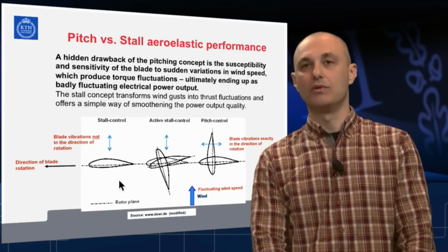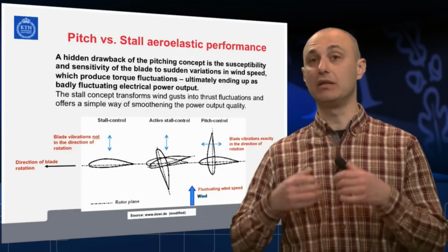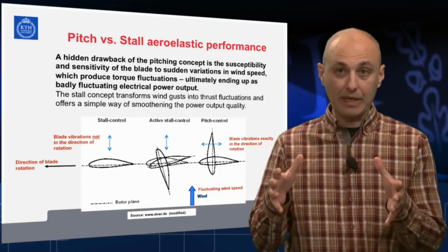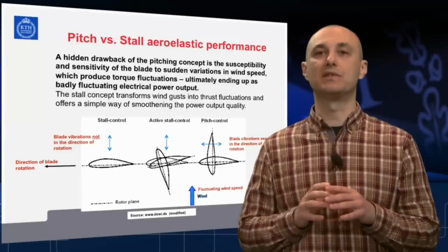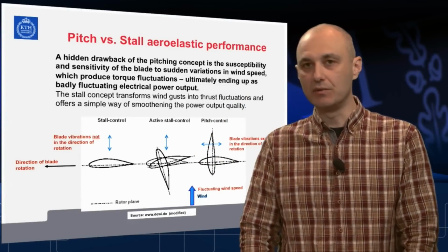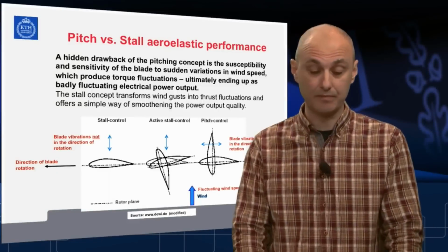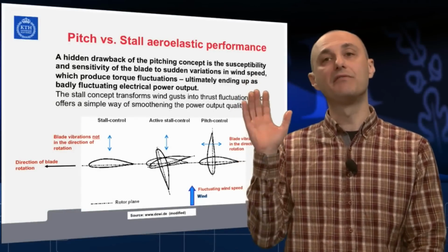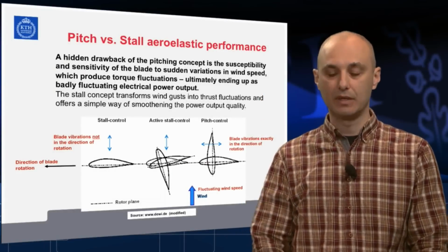The stall control, or the stall phenomena, really increases the loads on the machine while damping aerodynamic efficiency. That damping action represents itself by larger forces just pushing the turbine. If there is a fluctuation in the wind speed, and there always are fluctuations, the wind is never super stable, those fluctuations will be fluctuating or varying force only in the thrust direction, pushing the turbine.